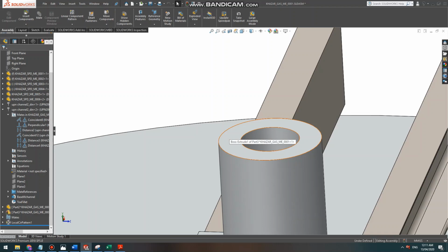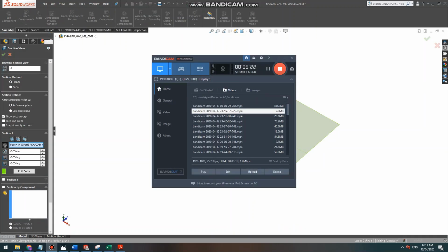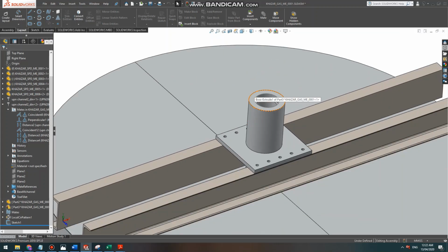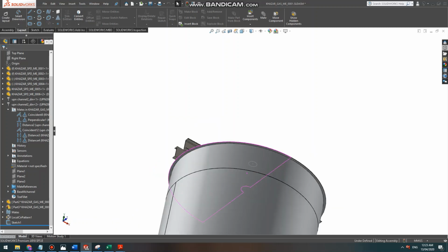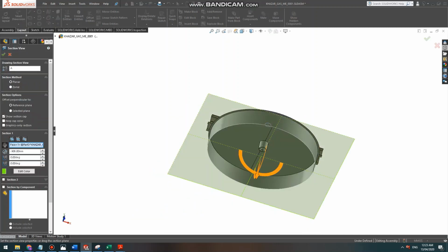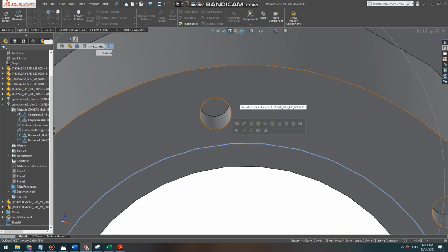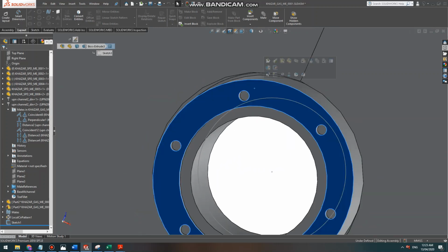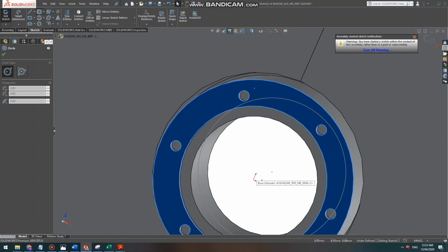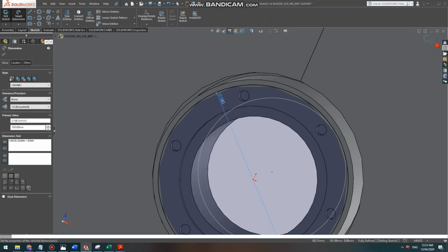So we will install bearings here, let me show you where. I think it would be fun to add bearings, but before doing that I want to make some modifications to the geometry. As you see, the outer diameter is too much. Let's say it's 140, this is 190. I think it could be less than that. It's over designed. So it's 160, so this one should be 180. So 180 is more than enough.